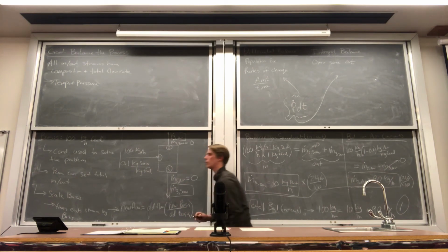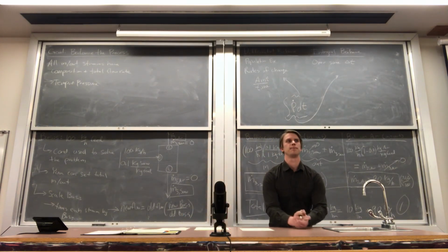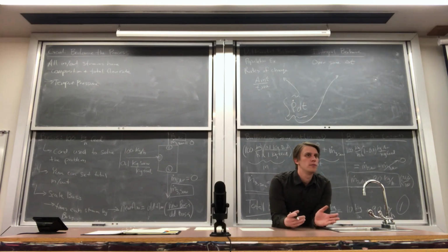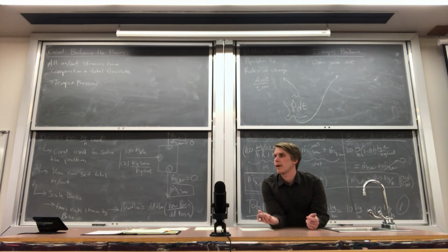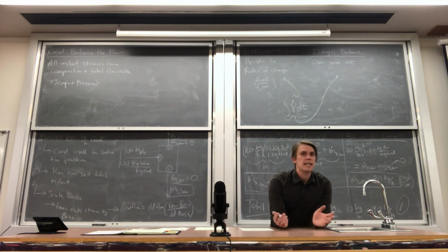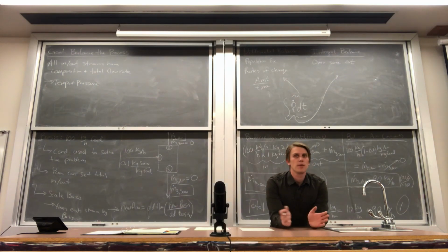And you apply that for every single flow rate in the process. Same idea could be made, for example, if I say I want a 50-50 mixture of sulfuric acid and water, right? You would solve that for maybe adding half a gram of sulfuric acid, half a gram of water. But then let's say you need 17 gallons of it. Well, then just times everything by that new basis, for example. I did mass to volume, but you get the idea on that one.